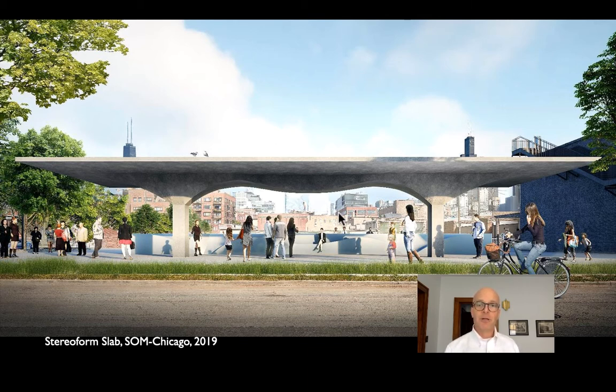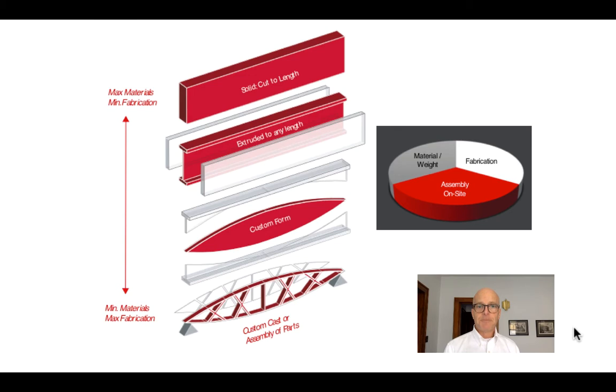If there are 30 or 40 of these, the weight of all that concrete that you're not using starts to add up, right? The savings start to add up. So in the longitudinal direction, we have ways of hacking the beam shape to save weight, to allow ourselves to use that weight either to span a longer distance or to put more load onto the beam. It's pretty effective. We can make generally more efficient beams and girders out of it, but it's not going to get us maybe to long span dimensions quite.